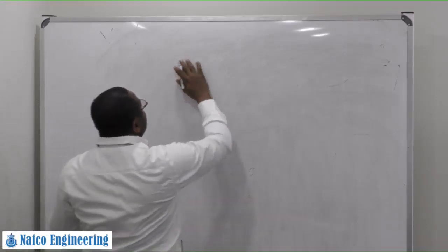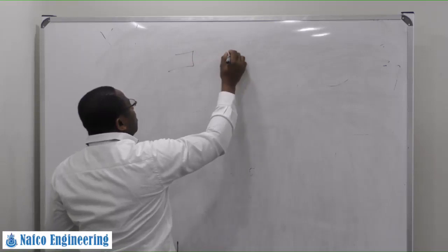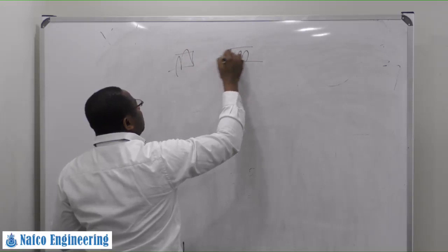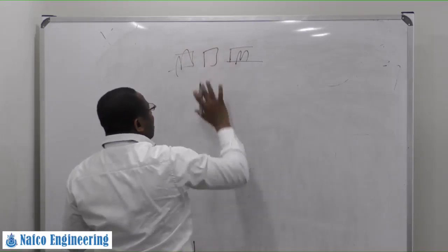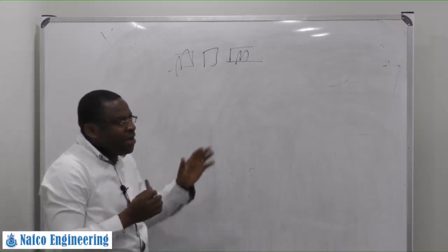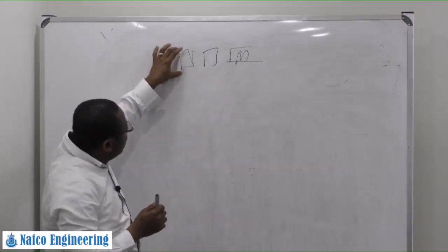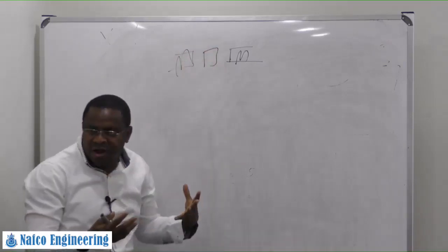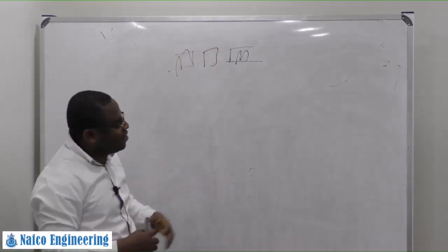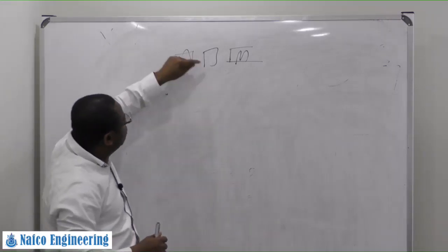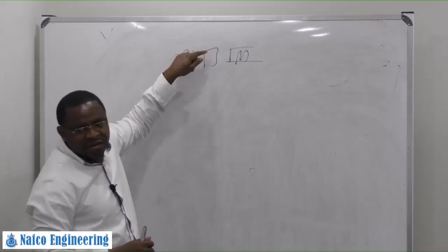Remember what we did in an electric motor, a DC machine? We have our windings, but internally there was no winding. So it was waiting for this one to be powered, and then induce EMF into this, and this one to create its own flux. But in this synchronous motor, instead of doing that, we are going to also excite this.